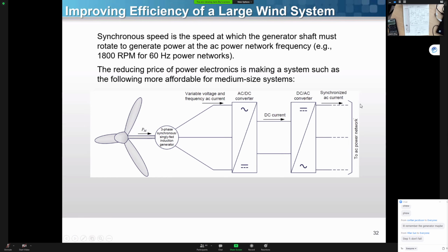So you might require 600 volt, 60 hertz here. The output of this inverter doesn't matter whatever. Usually you require a certain amount of DC voltage and current here, but the whole thing you pick up here will be matching whatever your generator down there is. So the output will be steady voltage and frequency. It will match whatever the grid is. Also, those inverters will synchronize with the AC voltage and frequency on the power grid.